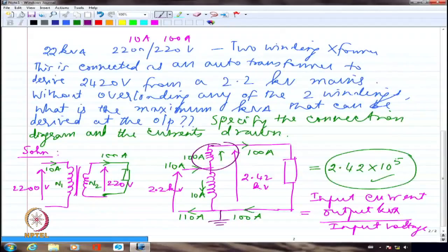See, we are generally looking at the power grid as an ocean. Normally we say our power grid is an ocean. That's the reason if you are generating only 1 megawatt or 2 megawatt, you say that you are putting a drop in the ocean. So that's the reason we normally call the power source generally as infinite bus. The bus is a bus bar or a junction point. From the junction point, you probably derive so many load connections.